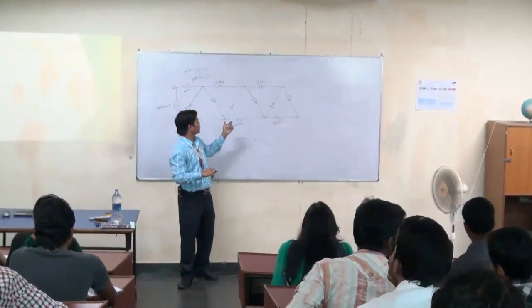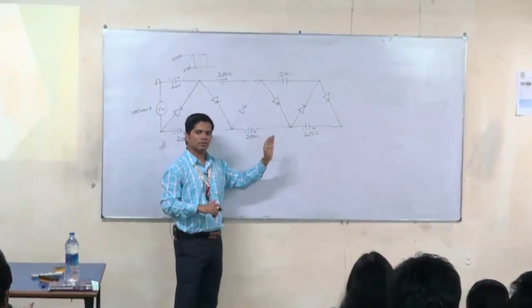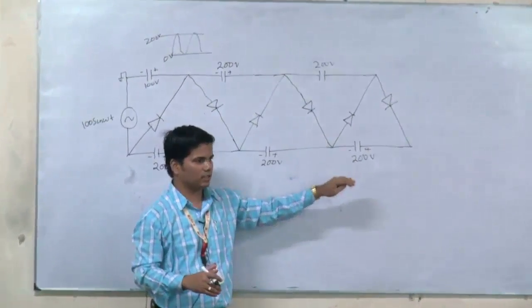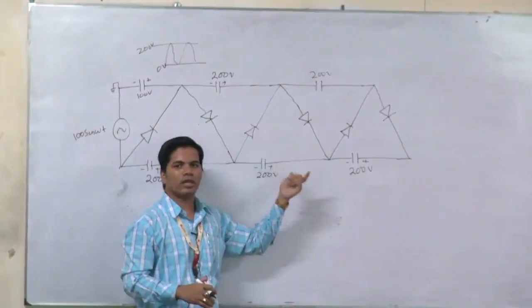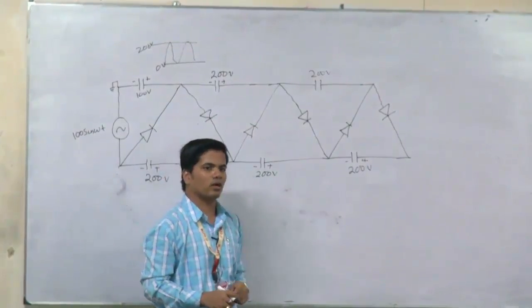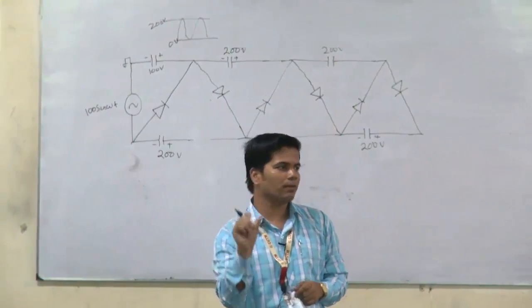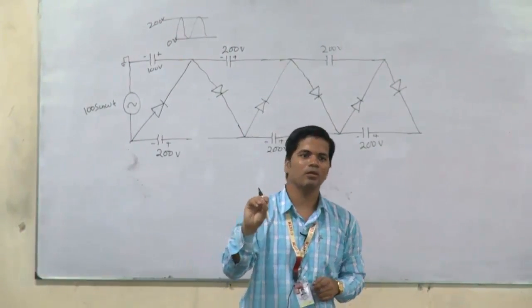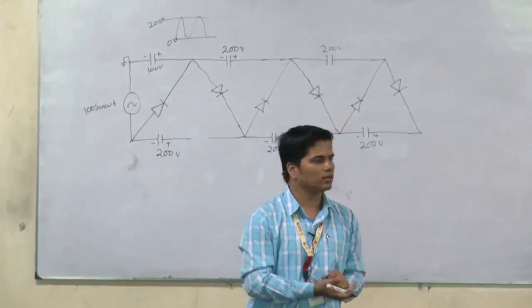But whenever we talk about the voltage multiplier circuit, we can have losses, because we are increasing the number of stages. Due to those capacitances and those diodes, we can have voltage drop. So we cannot get exactly that multiple of Vmax; we will get some value less than the multiple of Vmax.